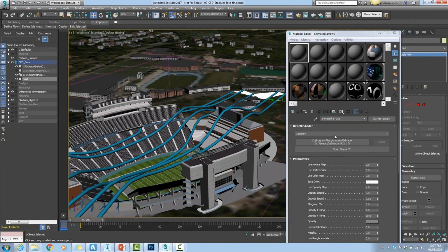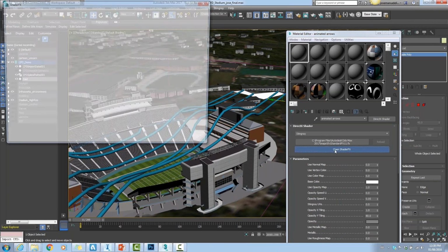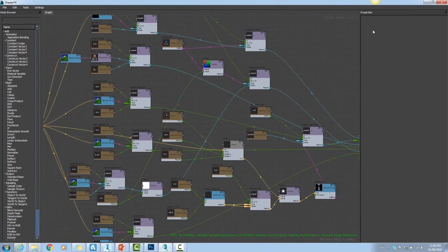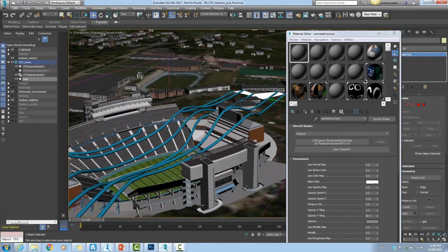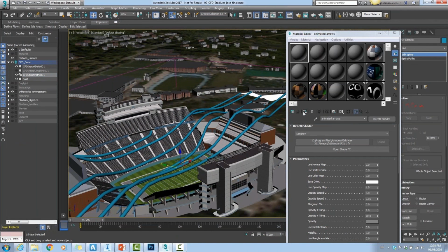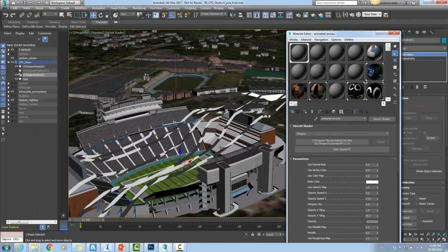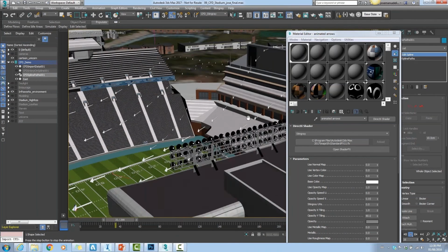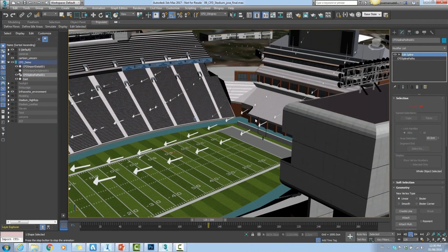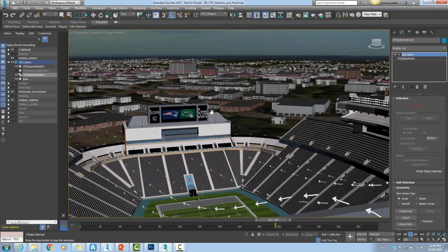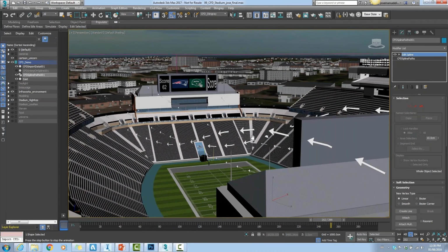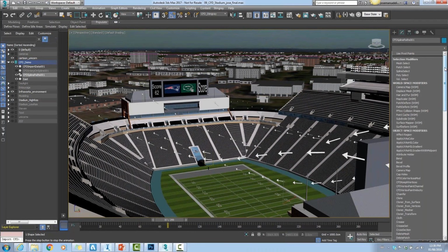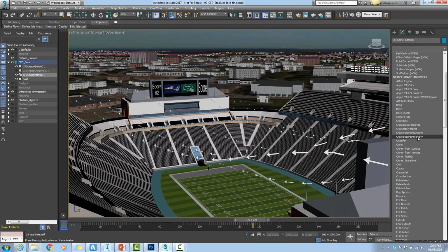All right, so now we got the splines in. Now we want to give this a visual style. We're going to leverage shader effects, or Stingray shaders, because this is going to go ultimately into Stingray. And we're going to create animated arrows to interpret the wind as it's flowing through the stadium. These are all capabilities that are very easily achieved using the Stingray shader or the shader effects platform inside of Max. Furthermore, we're also going to visualize the velocity that comes in from that velocity field, or point cloud, or how fast the arrow is moving.